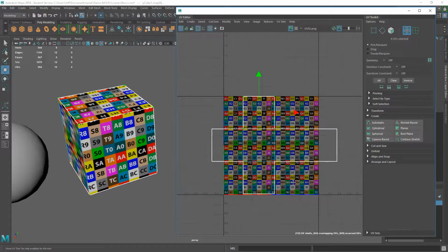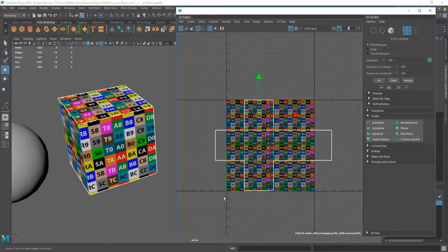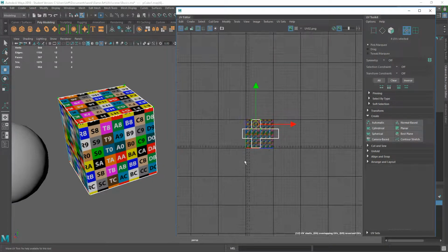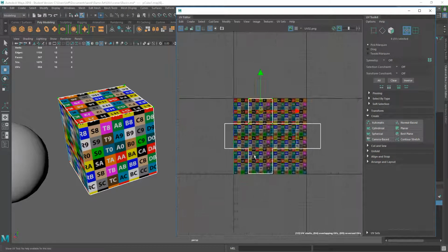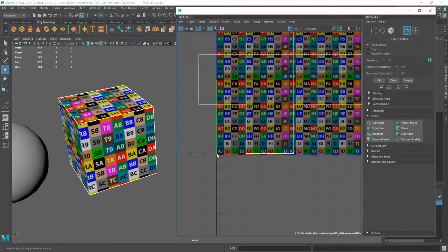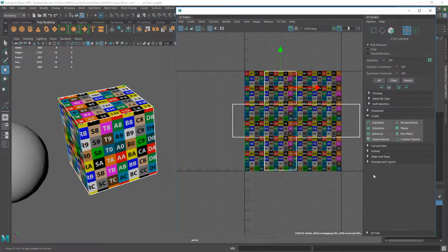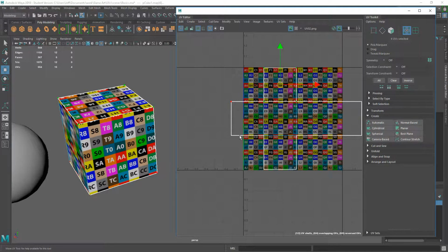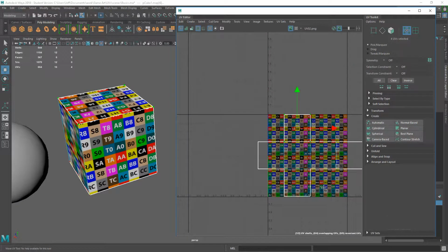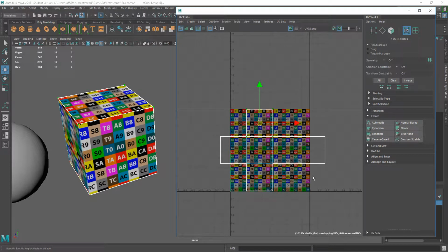And with that, one of the main things is, depending on the software you're going to, if I'm going into a game engine, then I need to keep my UVs within this first tile. So you can see as I zoom out here, we have all these different tiles. What we're wanting to do is use this one here. So they have numbers on there. So we want to use a range from 0 to 1 on the U's and the V's. So this is our U, essentially our x-axis, our V's, our y-axis. So again, 0 to 1 area here, 0 to 1 here. We need to keep all these UVs within the area.